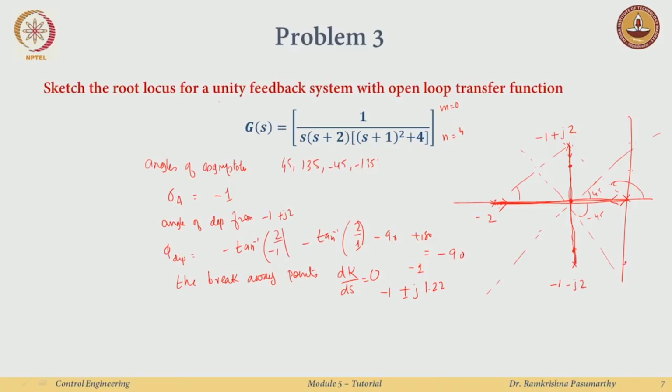This is 2, this is 1 here and I am having 1.22. Okay. So, guys come here, they even go away. So, this guy comes here and then maybe this guy will go and these two poles will meet here, right. This guy goes from here till here and they meet here. This guy goes from here till here and they meet here. Okay. So, something strange is expected to happen here. Now, look at even the asymptotes, right, they look as if this might actually come here and then cross the imaginary axis. So, does the root locus cross the imaginary axis?